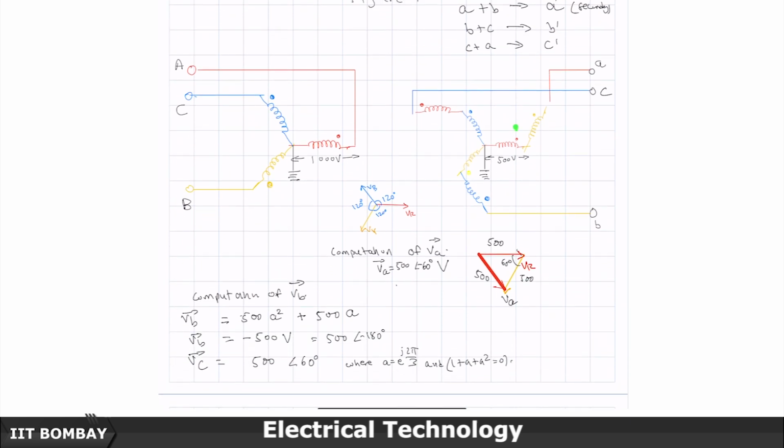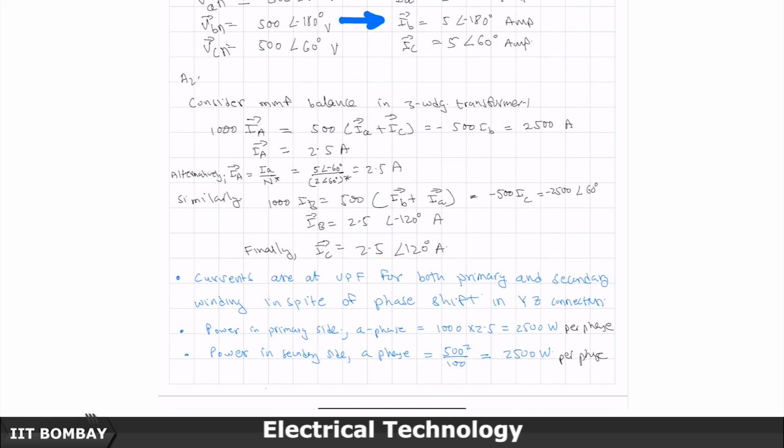So, A phase, where is it connected? I do not know what I said earlier, but let me be very clear. In this figure it is very clear. One thing carries the secondary side A phase winding current, and the other red one, what does it carry? It carries the secondary side IC current. So, therefore, this is the net demagnetizing MMF which is produced on the secondary side.